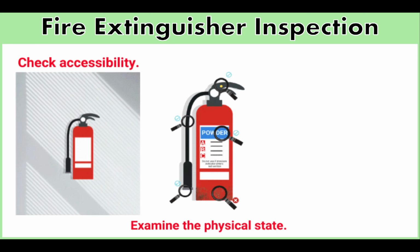Next, examine the physical state. You have to pick up the extinguisher to closely check labeling, overall condition, and physical defects. Look for the fire extinguisher's serial number and check if the fire extinguisher label is readable. Now you have to check if the cylinder or any other external metal parts are free of corrosion, dents, and other signs of damage. You also have to check the connection between the hose and the cylinder if it is secured. Inspect if there are cracks in the hose or leaks in the nozzle.